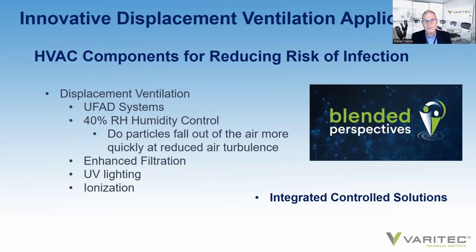We've picked up a new line of filters that offer MERV 14 effectiveness at less than 0.1 inch of pressure drop across the media, with filter change-out rates of 1 to 1.5 years. So this is certainly doable. And then if we added humidification to these systems, there are ways of controlling your indoor air quality efficiently, so an owner is not paying an operational premium to create the environment that his employees or occupants might seek to have.